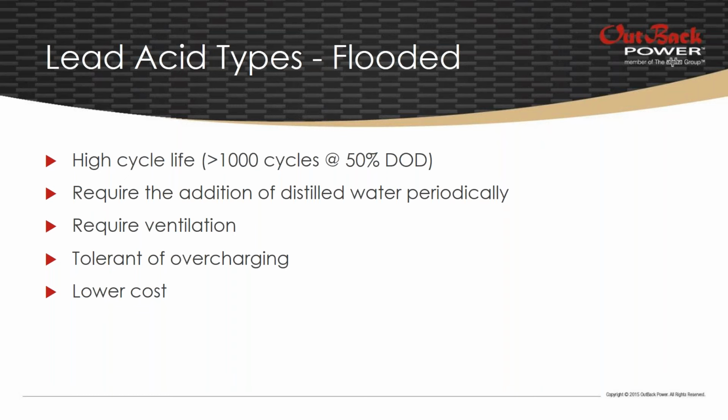Flooded batteries are really tolerant of overcharging. In fact, we do it on purpose when we do an equalization charge to knock all those lead sulfate crystals off. And a lot of it is because these batteries are so well researched that they're the lowest cost today of any of the renewable energy batteries.